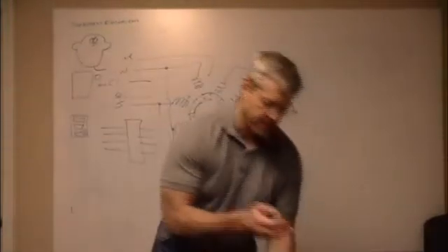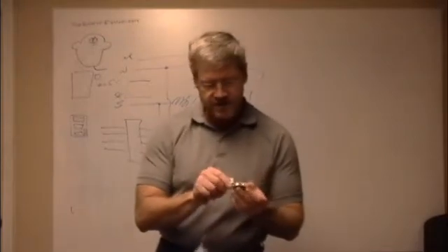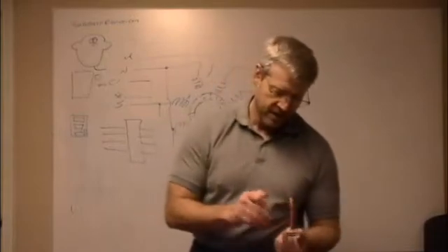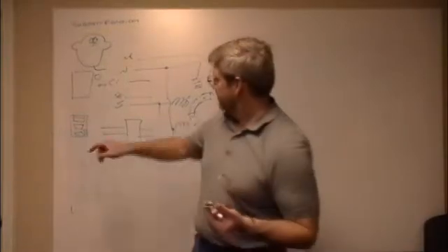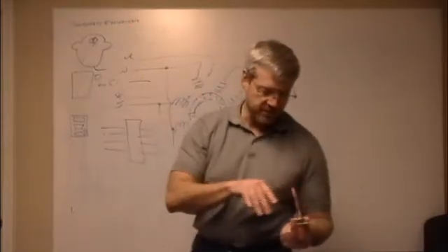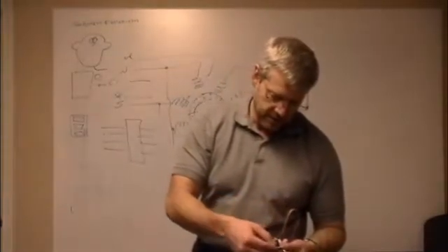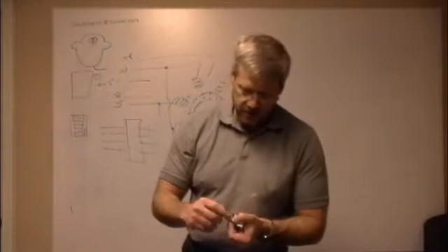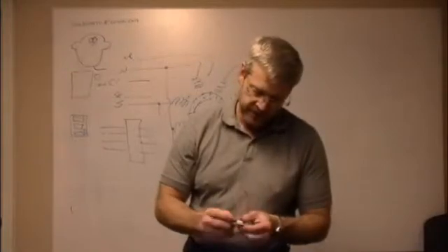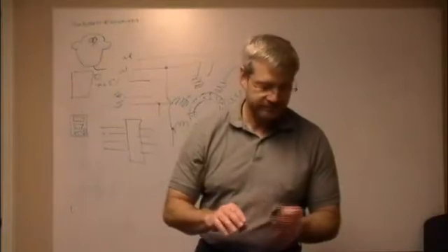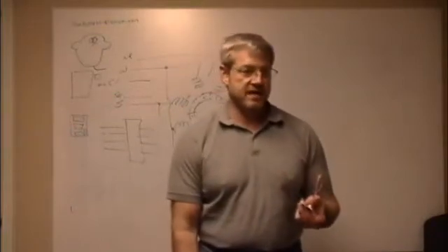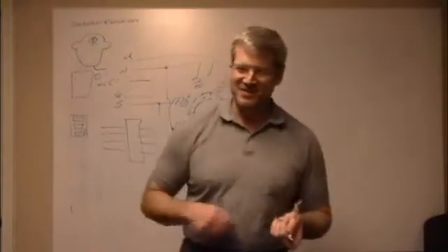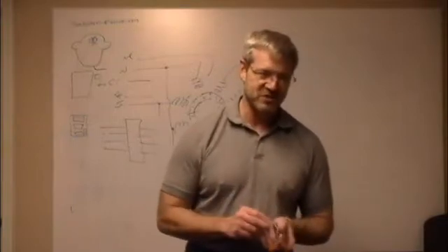So this guy, like I said, you can buy a box of 5 of these for $13. It just plugs in there like that. And then you bring 4 flying leads off here that are the four phases of the cable. And then you bring 5 to 12 volts in on that pin right there, and you take your ground off of that pin right there. And these LEDs light when each phase is lit. And I know this is exactly how you do it, because like I said earlier, for a change, I actually did the homework ahead of time this past weekend. So I've actually already been spinning motors.